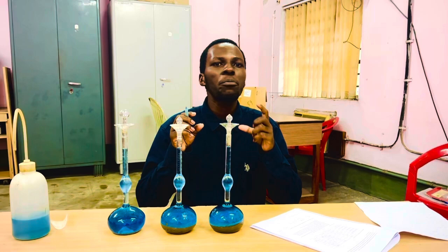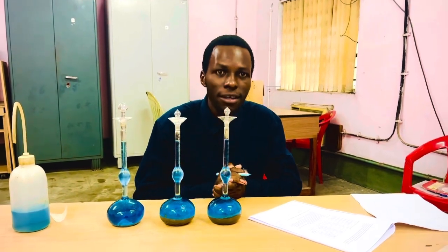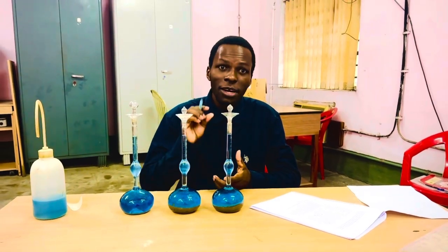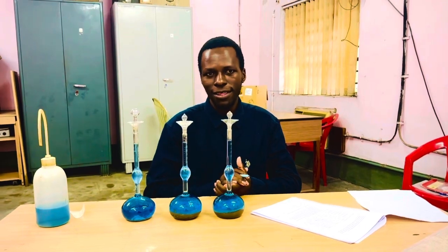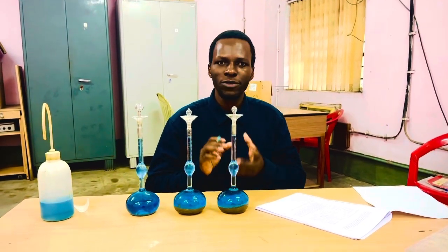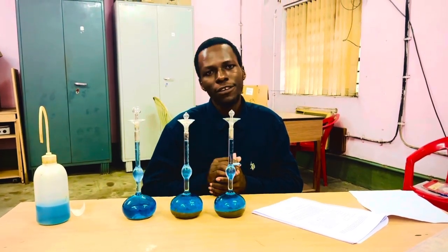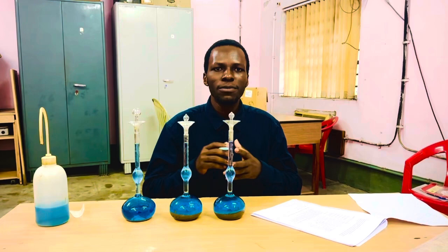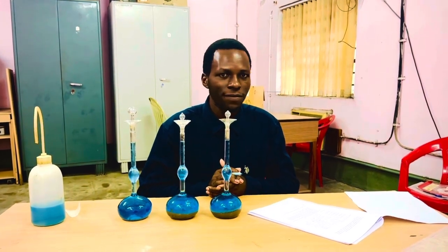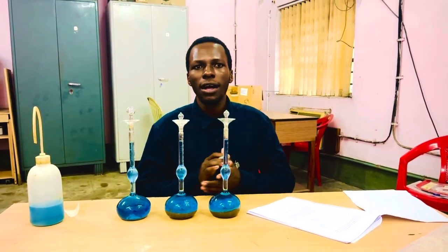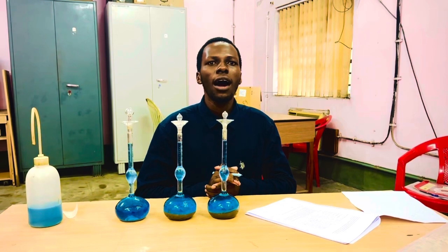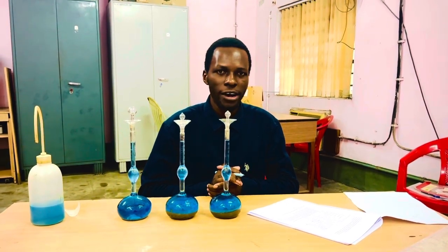Some of the precautions that you need to take is that make sure you use what? Kerosene, which is free from water. The moment it's having some water, then it will definitely react with the cement. Then secondly, ensure that you put your cement carefully so that you avoid splashes of the cement outside, because if you waste it, then it won't meet the actual weight that you took, which was 64 grams, okay?